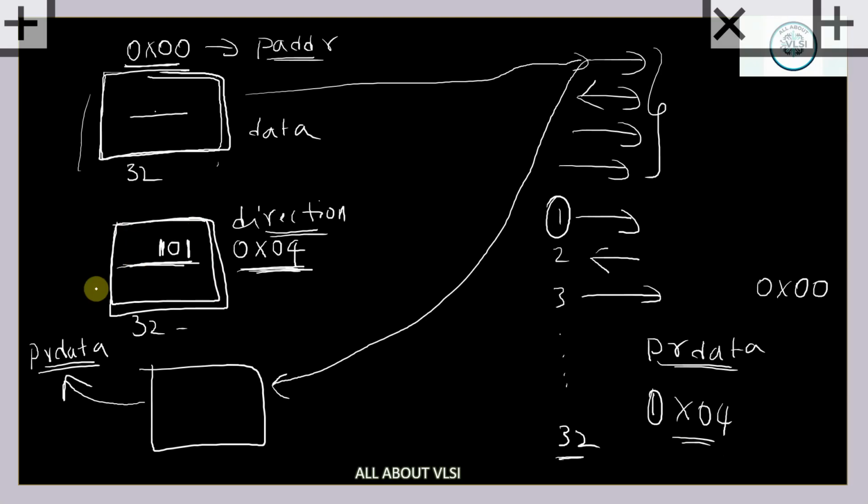That is also very important. Let's say you are going to write something, and if something is stored inside the register, that is a problem; now you need to know. That's why we are using these two conditions. And the third condition, third address, is 8. If you provide this address, then whatever data is being given from the GPIO pins and stored inside the register, you can access it by providing this particular address using the PRDATA signal. This is what we are doing.